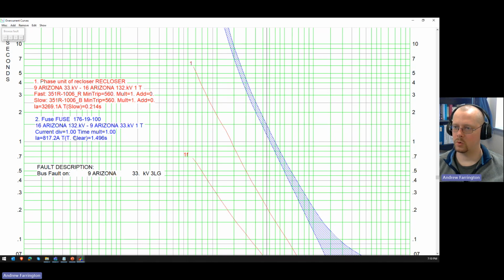The other thing that you can do to help figure out what the CTI is, you can add a time difference slider. I'm going to remove this one just for clarity. No, that's what I want right there. Yeah, just one. So now you can grab this and it'll show you the CTI, the difference between any two curves. And you can align that with your fault current. And now you can see what the difference is, 1.277 seconds. So if you did that math, that's roughly what you would get. You can't get it exact because you can't get it right to the pixel, but it'll give you a very good approximation for what the actual difference is.